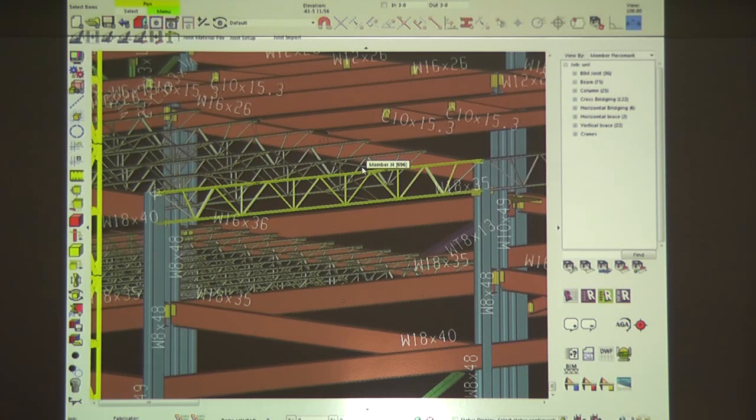That's why it's important. And right now here in Omaha, I probably can't say the name of it, but we're working with them to make sure that their sprinkler design software, all the sprinkler heads, which I know they're in here, you see one there, one there. Well, that piping up in the ceiling is 3 or 4 inch round piping. And by design, you don't want a whole bunch of elbows in there. You want to get as straight runs as possible.